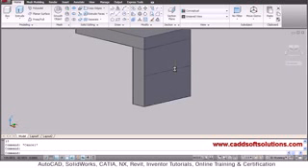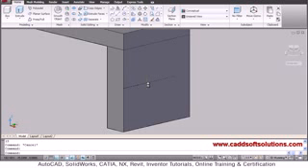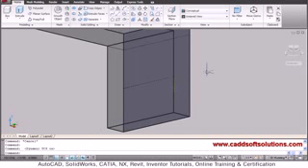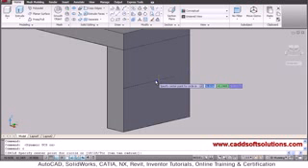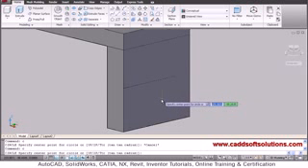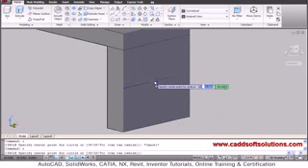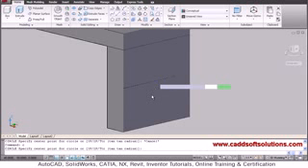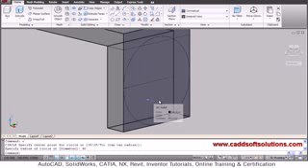So here we want to draw a circle. For that, to change the UCS automatically, you can also use the dynamic UCS. So just click on this button. So dynamic UCS is on. Just give the circle command, C enter. Then go inside this portion. It will highlight that plane, and just on this midpoint I want to draw a circle of 40 radius. So in this way it has been created.